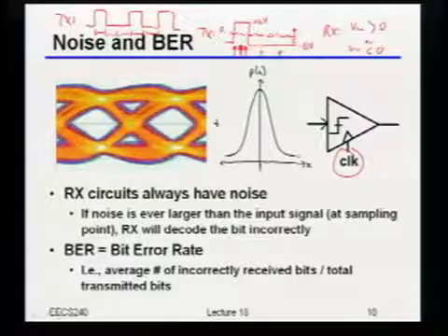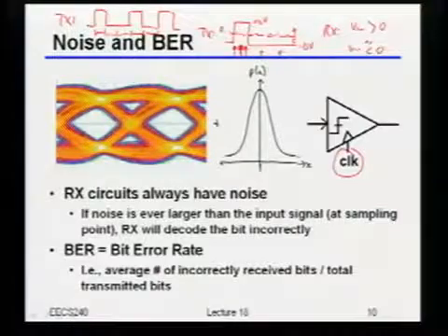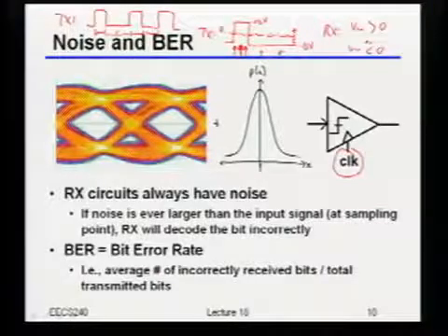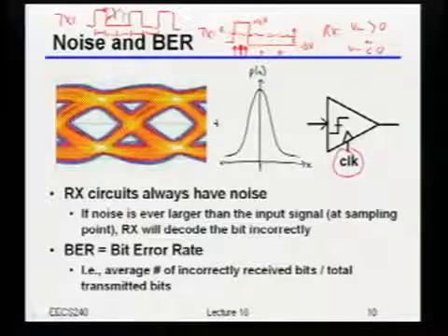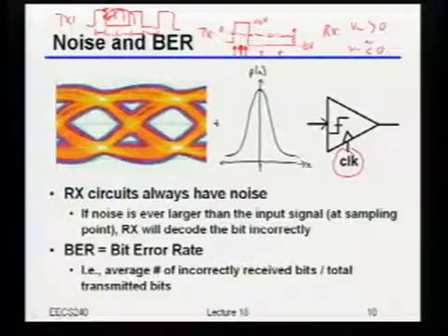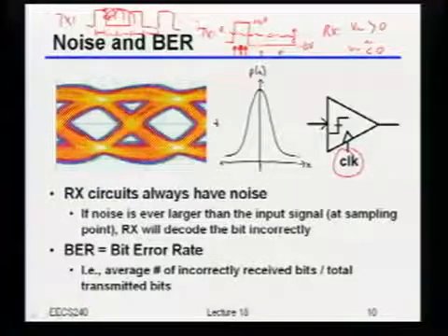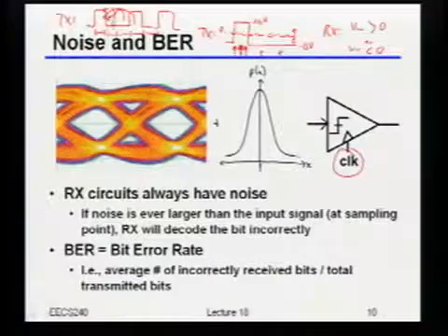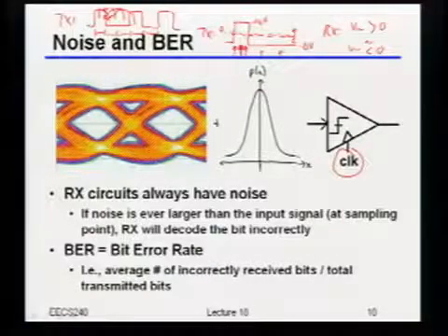All the eye diagram is doing is taking the time axis for each of those transmitted bits and overlaying it all onto the same spot, okay? So rather than continuing my time axis always from left to right, every bit period I reset it and draw the same thing on top of each other, okay?